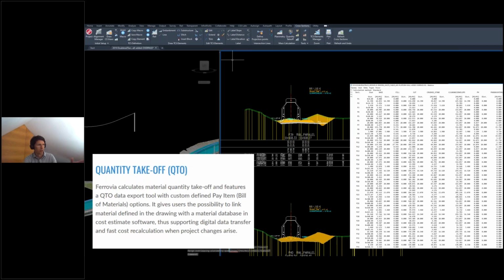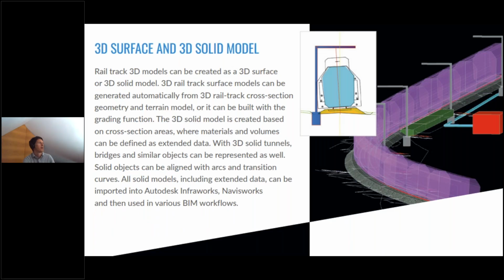As you saw today, there are two ways. One is the traditional way, when you calculate that and get into this table, which can also be opened in Excel. Or you can store all the volumes into the model, into the IFC, and then get the data values of the volumes from the quantities from the material directly from the IFC files. Okay, not just solids as we saw today. As I showed you before, with the string lines that are there, we can create surfaces as well.